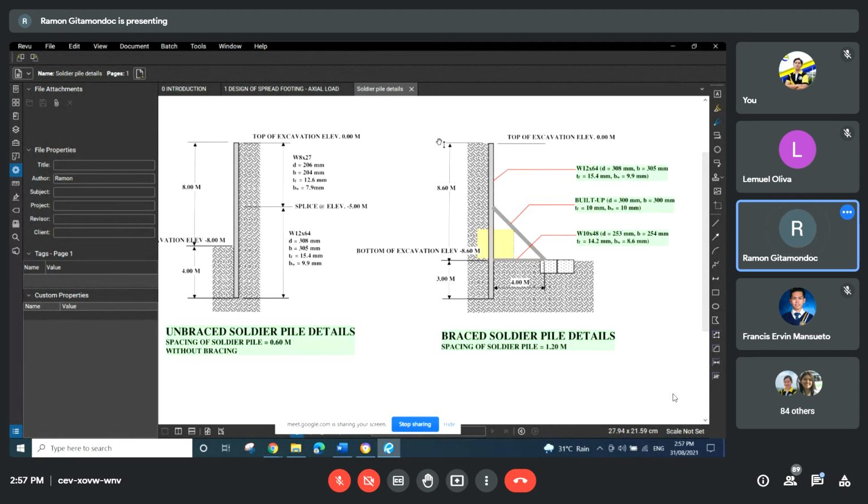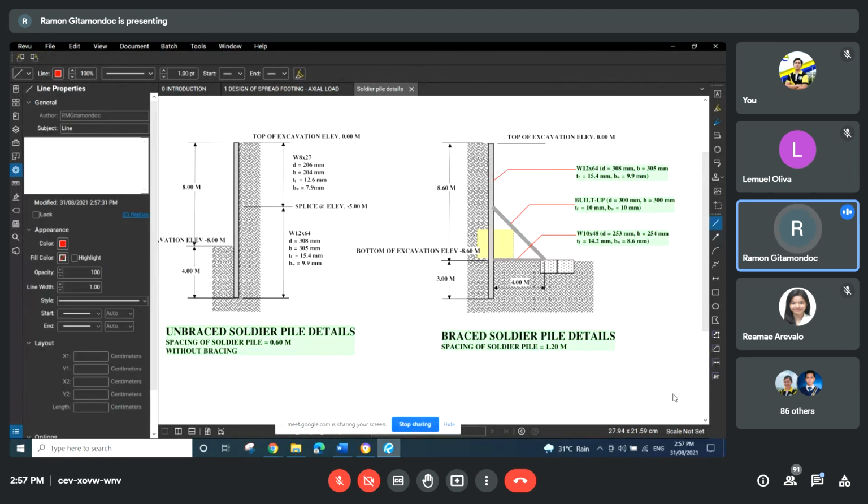But for this type of excavation, what they use is soil nailing, no? For soil nailing, you drive a hole through the soil and put some rebar, then insert some concrete grout, no?